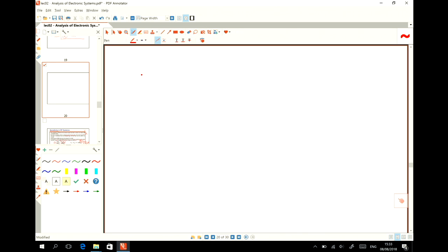All right, I have a source. I solve it for a source, and it's exactly similar for an antenna, okay? So I have a source, and this source is Vs. And it has an internal resistance of Rs. This is my source, and then it connects to my load. We say that we have a maximum power transfer from our source to our load when Rs equals RL, fully matched.